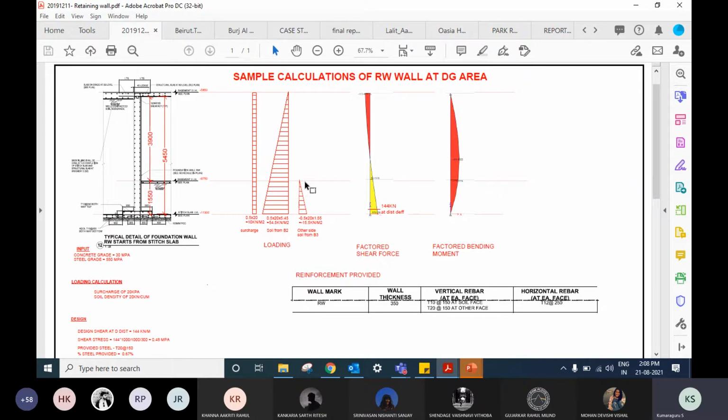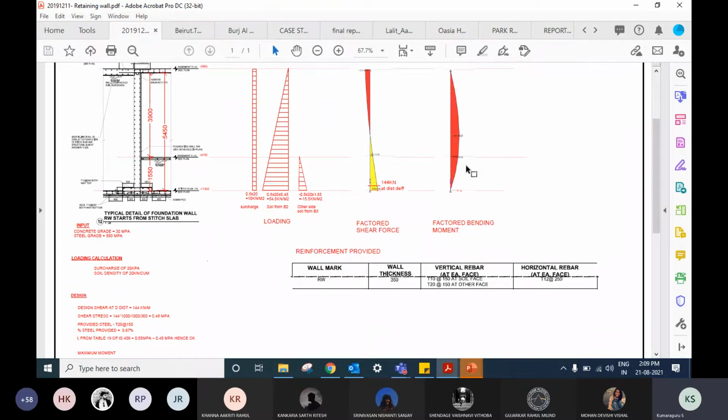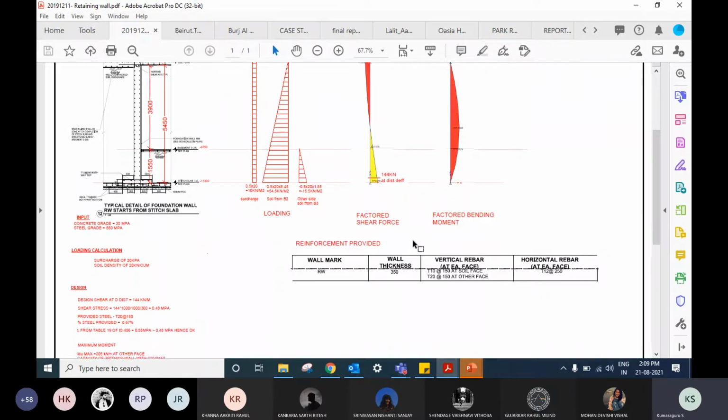That's it. There is no passive soil pressure in the current case, so you can neglect that. Now you add these two loads, and you get the total value, which is W. So WL squared by 8, multiply, and you'll get the bending moment, the demand bending moment. Fine. Once you do that, you need to now design your cross section.